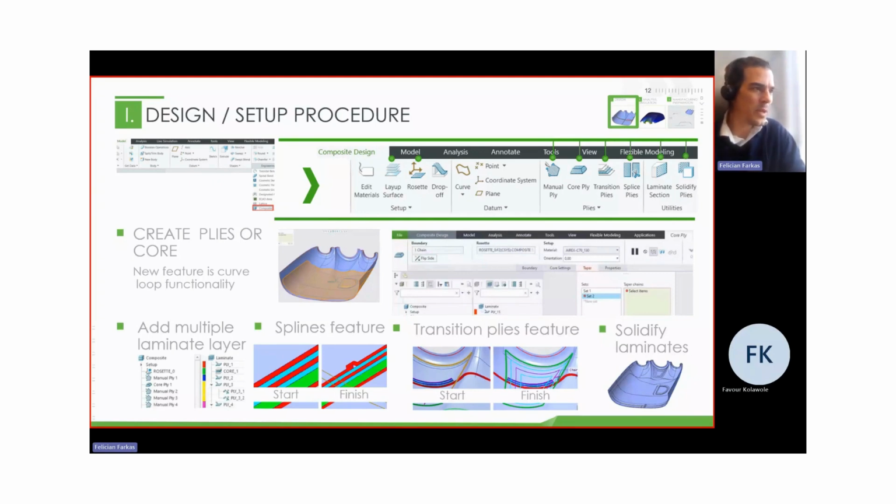Then we need to define the rosette reference corner system, the ply orientation and stacking direction. Then on the third and fourth dots, you can see we create the actual plies, the layers. It can be either a ply or a core.